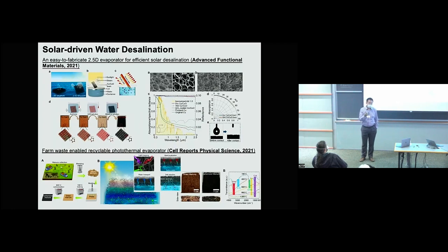And the cow manure, what is the main constituent? The main constituent of the cow manure is just cellulose fibers, just natural carbon. We don't have to use carbon nanoparticles or carbon nanofibers at all. We simply use the natural carbon waste material. So we brought a bucket of cow manure, and we carbonized it up to 600 degrees Celsius. It kills all the bacteria in the cow manure, and then we use some mechanical molding to make the carbonized cow manure based material. This material itself is a carbon-based porous structure, like a carbon foam, but with extremely low cost.